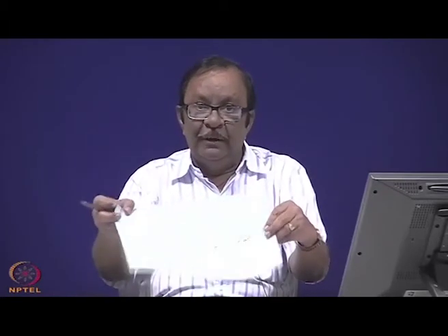So, ideally, if I want to follow the sun's rays all the time, my reflector has to have 2-axis tracking from east to west and keep rotating up and down, because the sun goes from east to west along an arc, and that arc angle depends upon the season, right. So, if you have a surface, you will be going from, let us say, east to west. In that process, it may also be swiveling, in order that the sun's arc will be in the plane normal to the aperture.